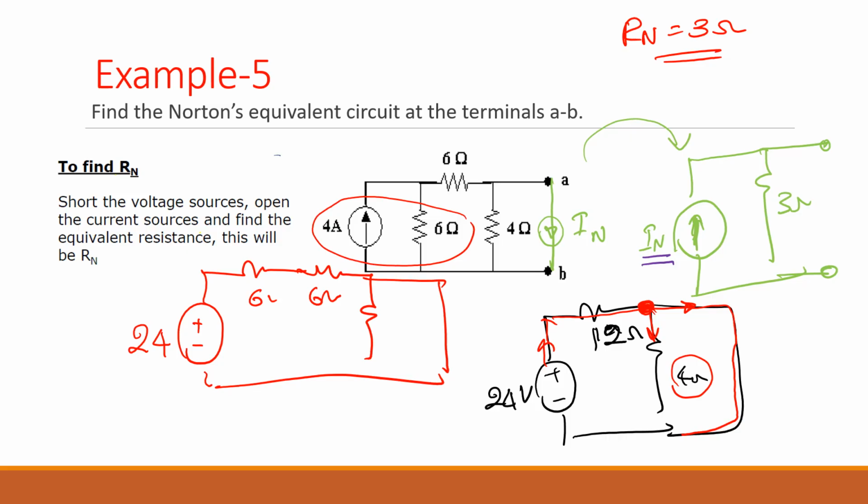So when there is a short circuit, the current would like to go in the easy path. So it's avoiding the resistance. When there are 2 resistors, yes, it is splitting between the 2 resistors depending on the current division rule. But whenever you have a resistance in parallel with the short circuit path, the current will never follow the harder path. So current is always going in the easier path.